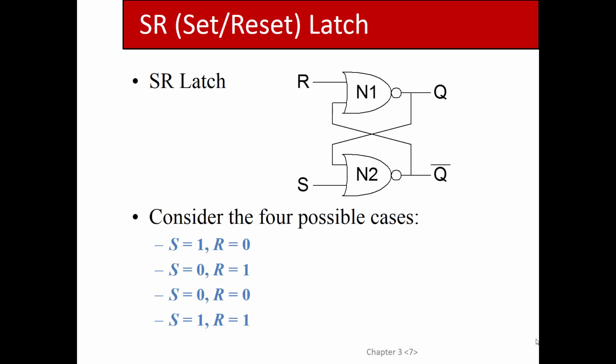You guys following this? I think I've screwed this explanation up. So the bottom line, to describe it another way, is if I put a 0, 0 for R and S, these NOR gates essentially become inverters, right? You guys with me? If I put a 0 into a NOR gate, then I'll look at the other input and the output, and it just becomes an inverter.